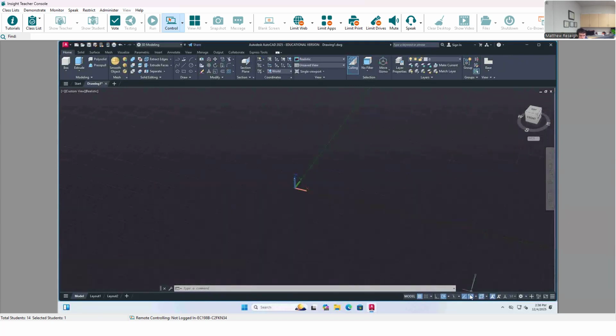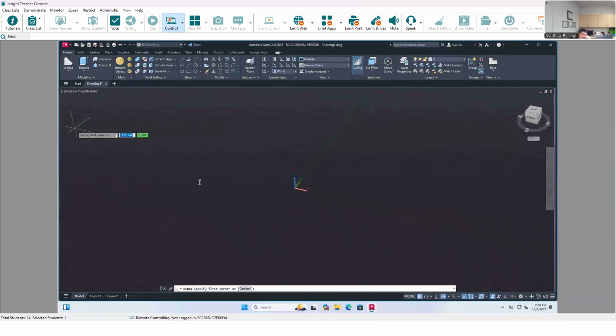So I leave on my 3D snaps and I leave on my 2D snaps, which this one has not that much selected. This might be the default that you guys deal with too, so I would turn on some of these. I'm not going to need tangent or maybe geometric centers though. Okay, so I got my snaps on. Let's do just a quick something that could use a top, front, and right side view. So maybe this wedge. I'll do a wedge shape here on just this profile. So I'll do a 4x2 wedge. I'm going to zoom in here a little bit.